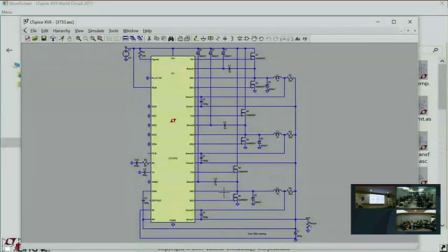Now the point of sharing the current among multiple phases is not really so much to get more current through the switcher. If you have a switch mode power supply and you just want more current, you should first consider using larger MOSFETs. It's much more direct. But the reason for divvying the current among multiple phases is that you can stagger the inductor ripple current phases so that when they sum on the output, the ripple will destructively interfere, and you can make a switch mode power supply with a very low net output ripple. Depending on the number of phases and the voltage ratio between the input and output, they can precisely cancel.